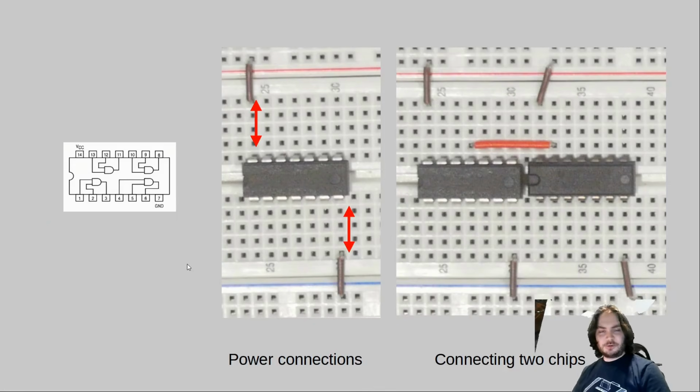If you haven't seen a breadboard before, the gist is vertical aligned holes connect to each other internally, whereas horizontal don't. When you hook up these logic chips, generally there's a little circle cut out that's like the top of the chip. On the one end, on the right, is going to be the positive power input, 5 volts, and then a ground input on the opposite corner.